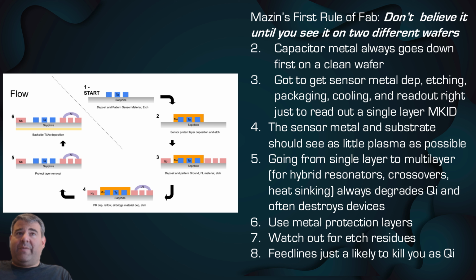Feed lines, those wires that bring the signals into and out, have to have those crossovers. They're also like 0.5 meter long when you unwind them, with 2 slots that are each 2 microns wide in our design that can't have any opens or shorts. It turns out the feed line fab quality control gets us more often than other things in this. It's one of the hardest things to get your feed line yield good. That's why we've been working with Lincoln Labs with those air bridge devices, which have had nearly perfect yield.